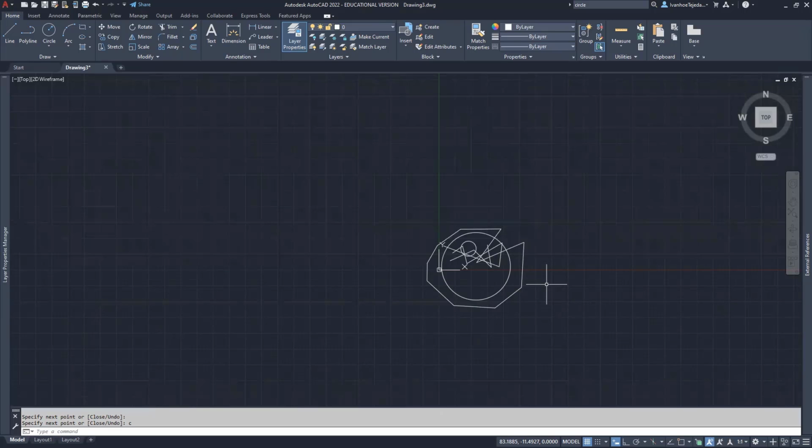I want to see the extent of it. So what you can do is you can take that wheel mouse and you can give it a double click. And when you do that, that's what's called a zoom extents. Now, on my mouse, I always seem to have issues trying to give it that double click and getting it to work. So it doesn't always work.